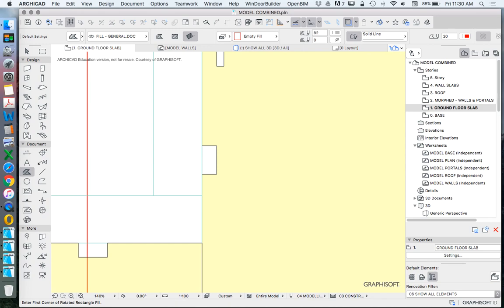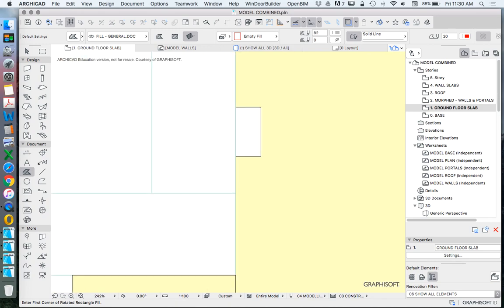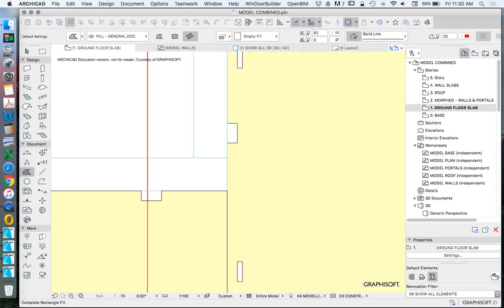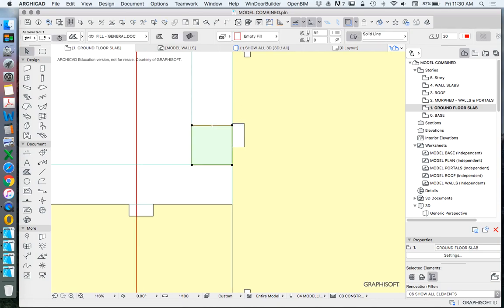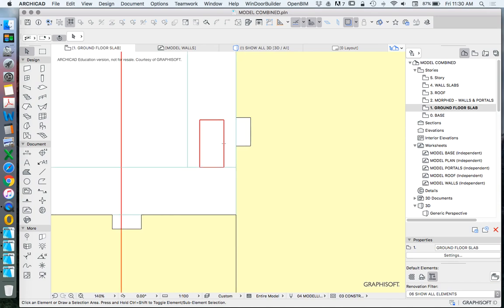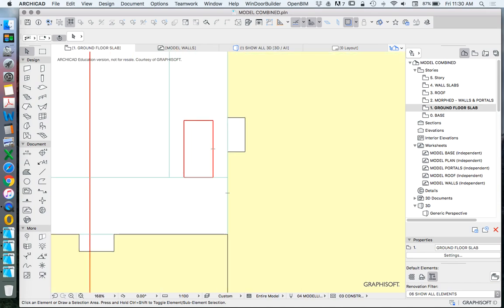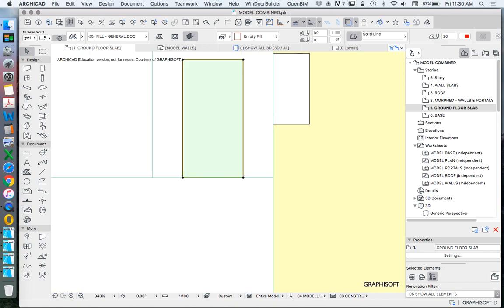I used a fill to be able to draw that shape. What do we see this is? This is 2 meters. Let's make this one 2 by 2. And then we will offset this one a little bit. 500 millimeters in, 500 in, and then we need to, if we want to key it, make one side, the side that it connects to, slightly smaller.